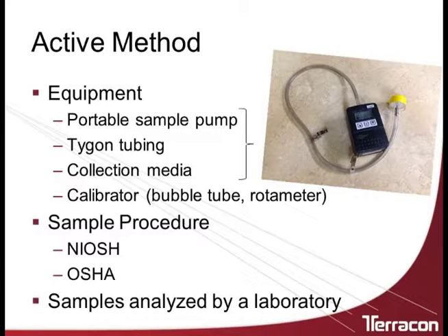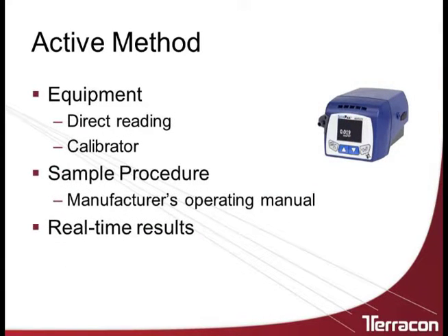In the active method, there's also equipment that can be used that provides direct reading capabilities. Here is a particle sampler. It also uses an internal pump, and it will pull in the particulates and you'll get a readout. The nice thing about this is that it does provide real-time results. However, you're going to have to follow whatever the manufacturer's operating manual says for making sure you're collecting the sample the way it should be collected.